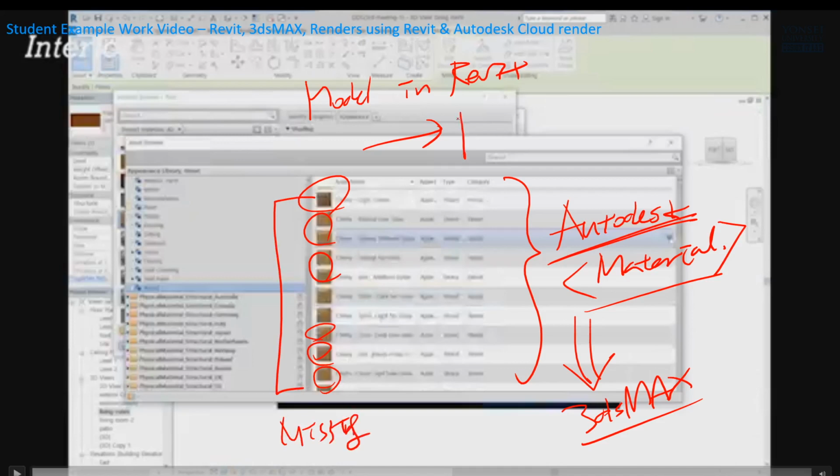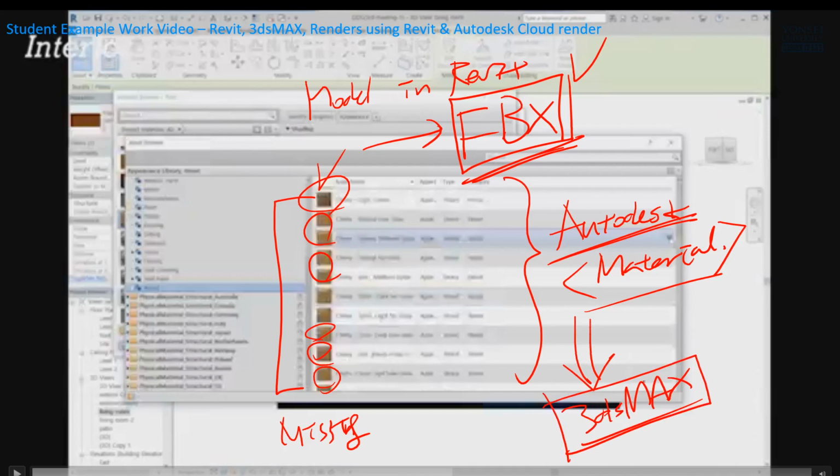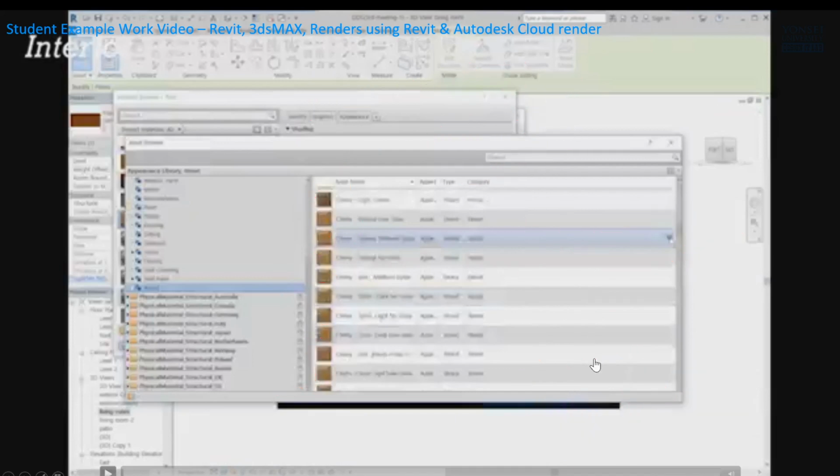That is why I'm saying use the FBX file. If you use an FBX file, you can keep this material. Sometimes some problems, some errors happen, but anyway, usually, thanks to the FBX feature, you can reuse Revit's default or your customized material, and it can be alive in 3D Max. That's what I'm saying. But actually this example, this case, is only Revit-based visualization.